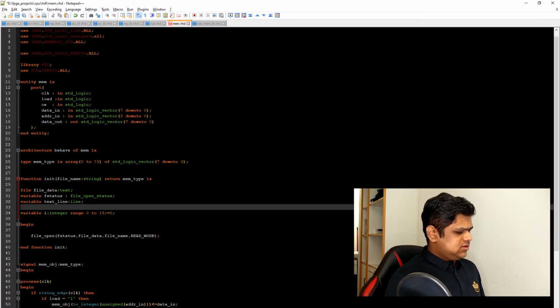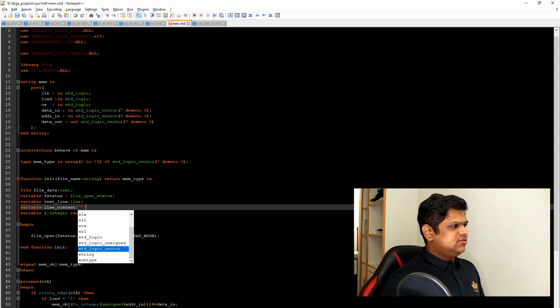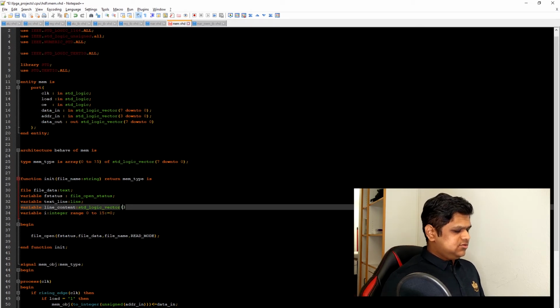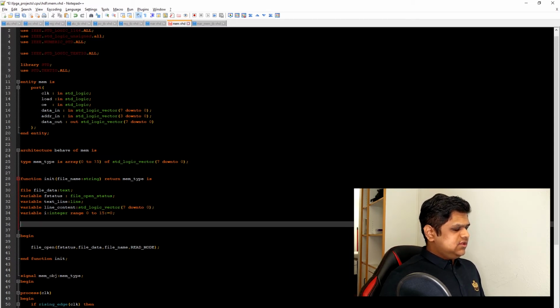Yes, we will need one additional variable called line content. This line content will be a standard logic vector of 8 bits. And also we will declare a temporary memory variable, so variable temp memory of type our memory type.